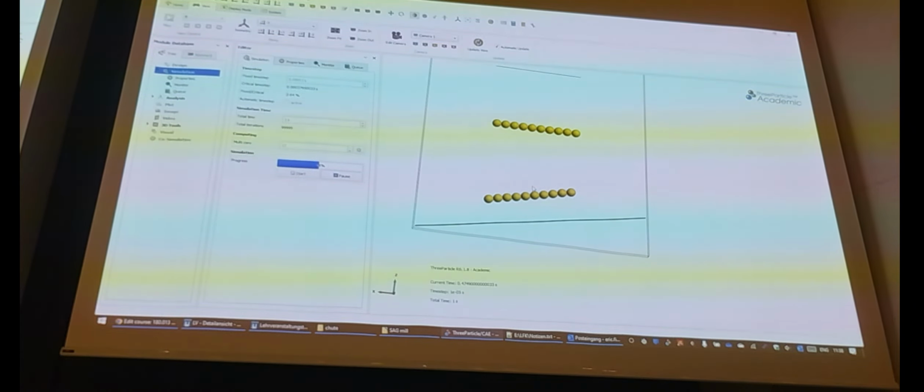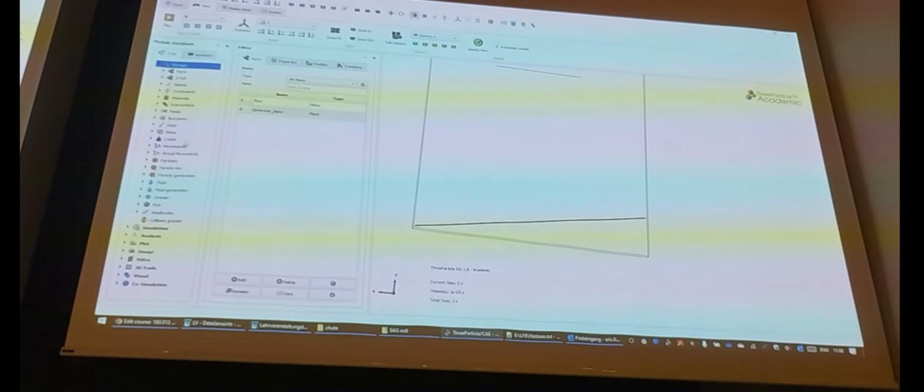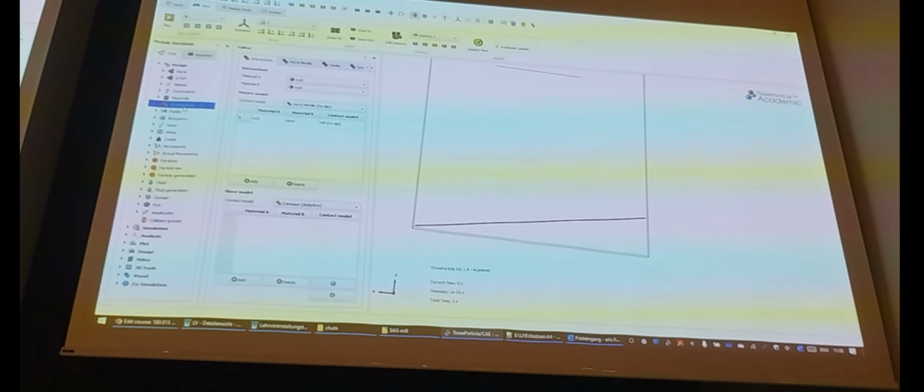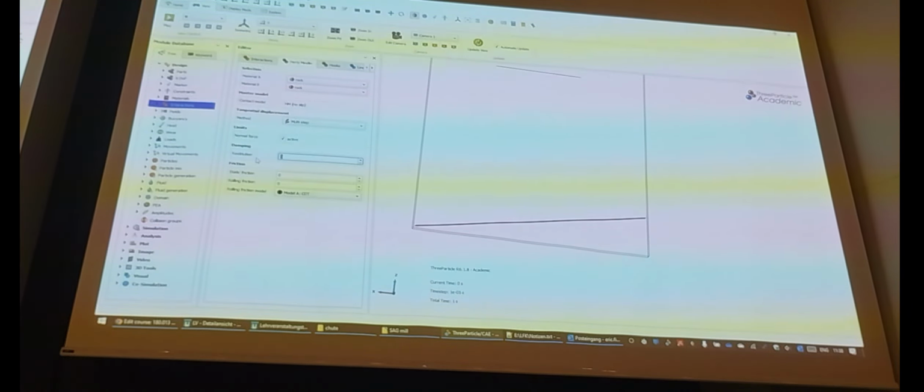Let's see from the side what's happening. They won't collide. Yes, they won't collide. Why? Because we didn't define the interactions between the same particles. Absolutely right. So we can go back, interactions, and we define rock at rock. Similar as before, but I want to have stone to stone, even with a little bit more damping, like 0.1 or even below, something like, let's say, real rocks. Rocks do not behave like steel balls. Rocks are more damping. 0.1, and static friction I choose just the same, so I have starting values.